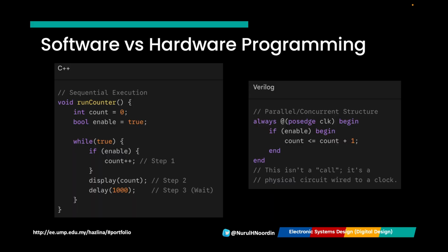At first glance, an HDL like Verilog might look incredibly familiar. It features a concise C-like syntax that makes it very approachable if you already know procedural programming. You will use standard constructs like if-else and case statements. But don't be fooled. Unlike traditional programming languages, in HDL you are not writing a sequence of instructions for a processor to execute. Instead, you are using code to describe the actual physical architecture of a digital circuit.